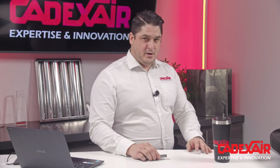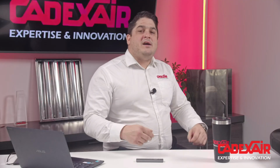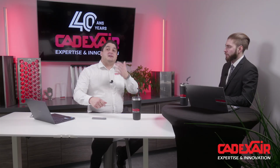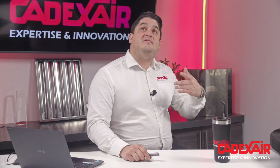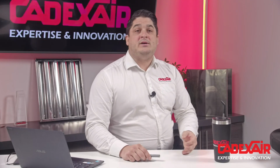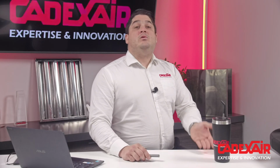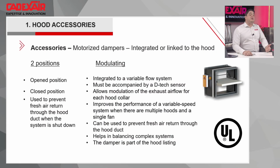So right now what happened is we have a shaft of 10 by 20 or 10 by 15 going outside of the building, and as per NFPA 96 we cannot put any damper inside the fan, the ductwork. The only place that we could put a damper is as a hood accessory. So we can use this damper to minimize the airflow return inside of the hood in case of negative pressure.